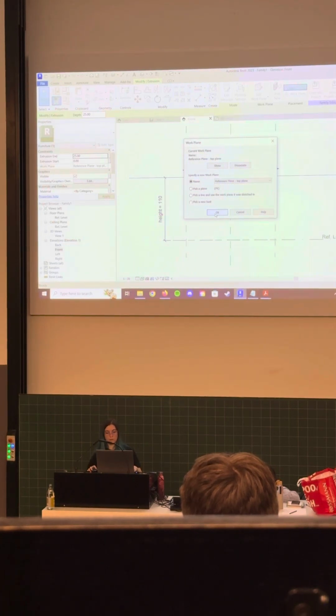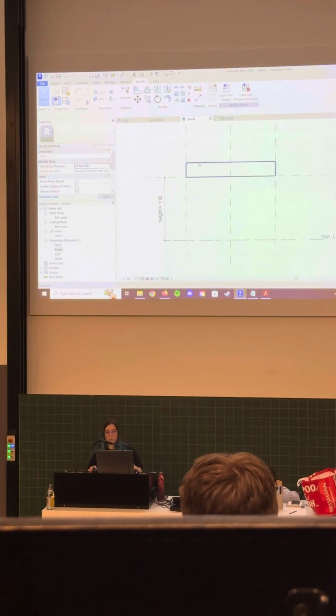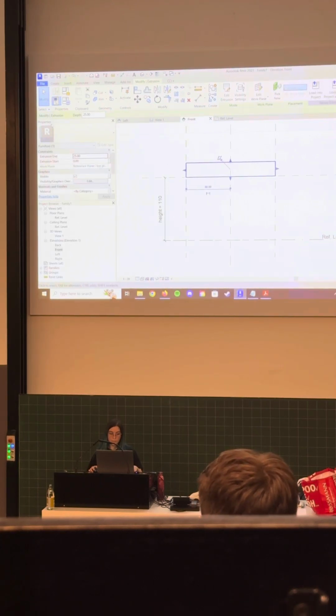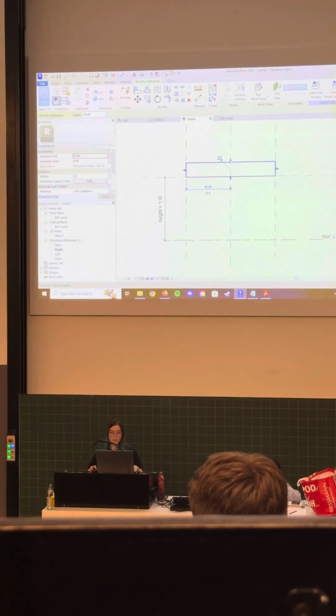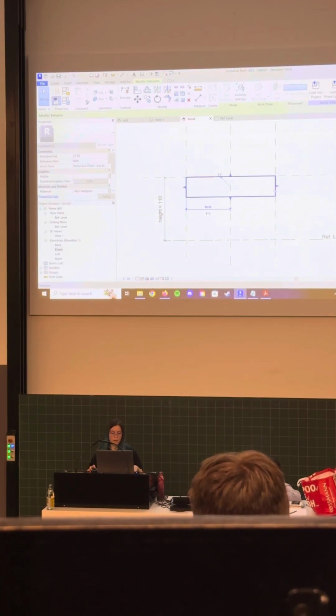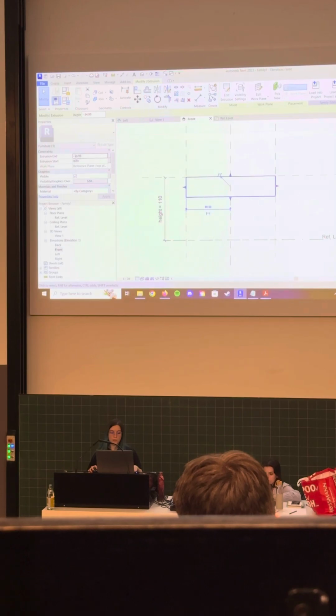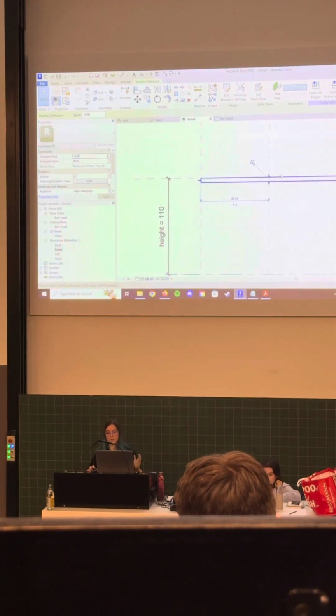And then press OK. So now to edit the dimensions of this one, we select it and we see in the properties window that we have the extrusion end and the extrusion start. Right now it's showing like this. We can also edit this by dragging it. We see that this value here will get negative. I will leave it at -5, for example, and select apply. So this will be the top of our table seen from the side.